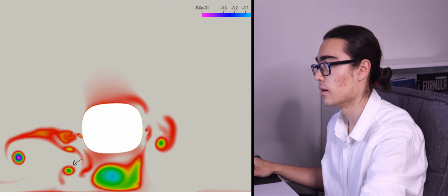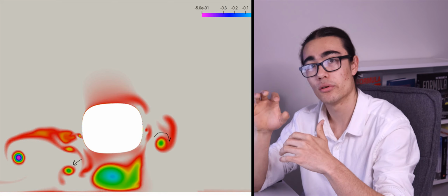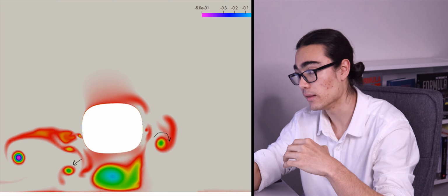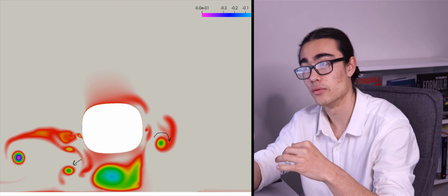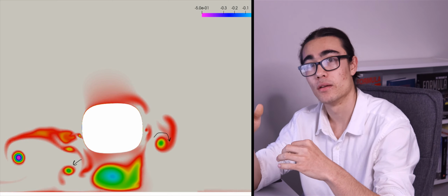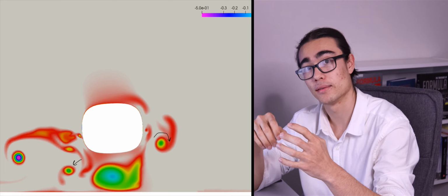We've also got our canard vortex going strong, quite outboard. Now we're not going to see the full effects of this because we're dealing with a simplified wheel geometry. So we've got no ducting, and we've not got the realistic turbulence that we'd normally see where air could actually pass through the wheel. Anyway, for what we're looking at, it was perfectly fine. Let's continue.